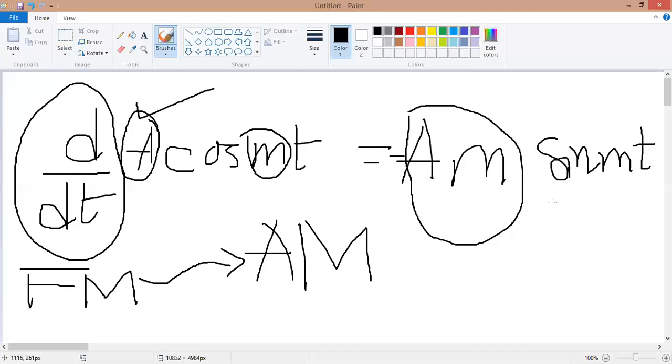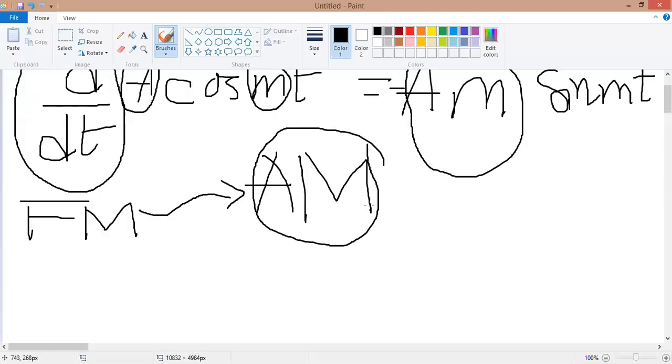And if it is an AM signal at the output, how do we demodulate it? What kind of demodulator block do I need? You can say, sir, it is possible using a square law detector, using an envelope detector, or using a synchronous coherent detection method.